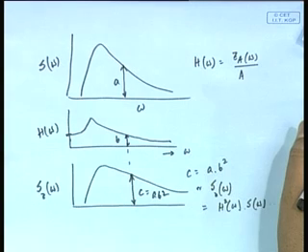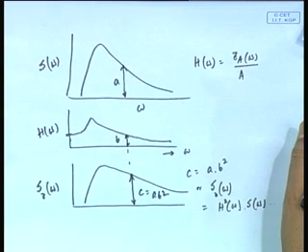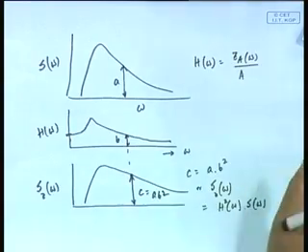Because it is a linear response function. After all, as I told you, for a given omega, let us say a given wavelength of 100 meters, if my heave was 2 meters for a 1 meter high wave, then it is going to be 4 meters for a 2 meter high wave, because a 2 meter high wave is two 1 meter high waves together, and both will give 2 plus 2, 4. So, it is as simple as that.